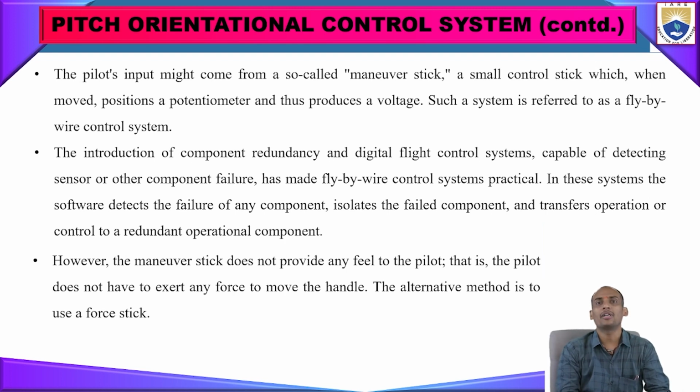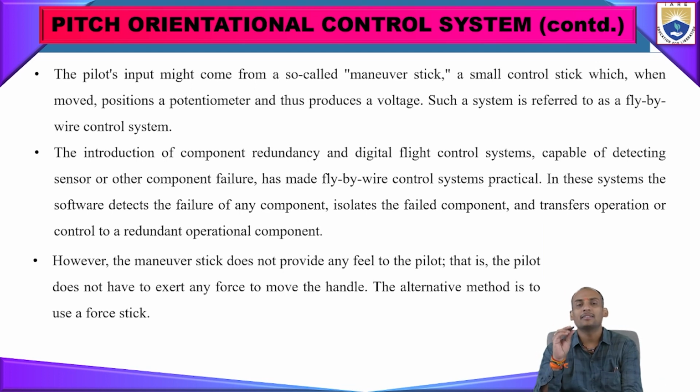However, the manual stick does not provide any feel to the pilot, so the pilot does not have to exert force or move the handle. So the alternative method is to use the force stick. I mentioned that one previously, when I gave the doorstep example.